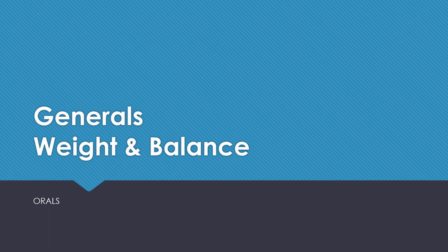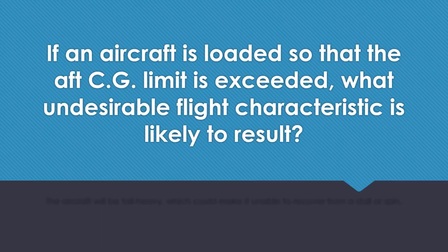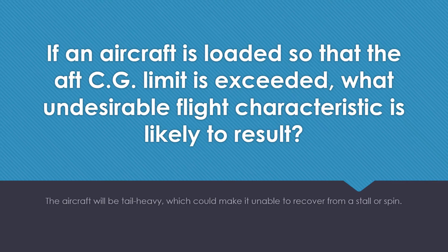Generals, weight and balance, oral questions. If an aircraft is loaded so that the aft CG limit is exceeded, what undesirable flight characteristic is likely to result? The aircraft will be tail heavy, which could make it unable to recover from a stall or a spin.